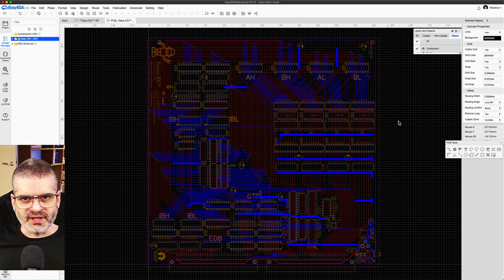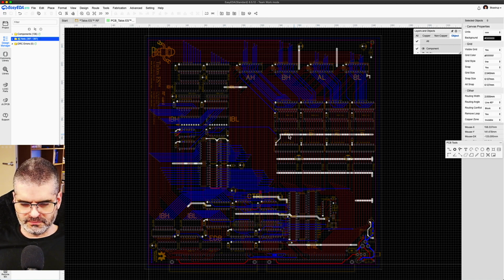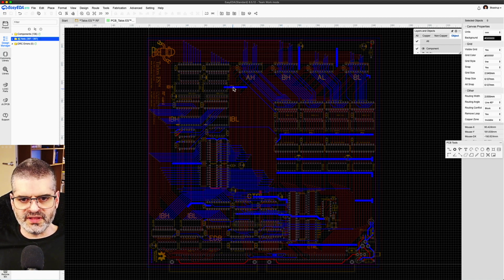So in blue, the copper fill is ground, but I'm adding dedicated lines to sort of stitch the copper areas on the top layer via the back layer and avoid these bottlenecks in different islands of copper fill. And that's what you see in these thick blue lines, and there are even vertical ones.